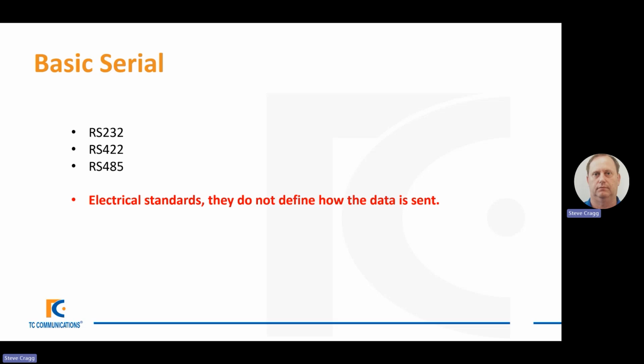So when somebody is explaining that they are using RS-232, it is quite possible to be compatible with RS-232 in the fact that 2 devices have the same voltages. In other words, they use the same voltage for a 1 and the same voltage for a 0.